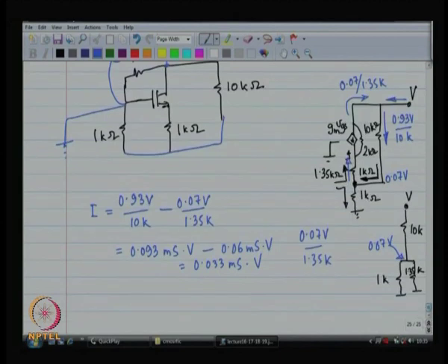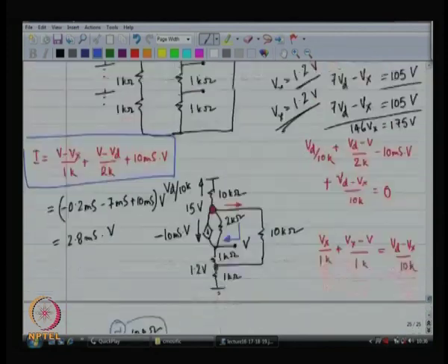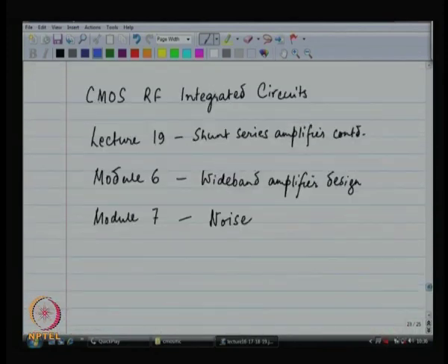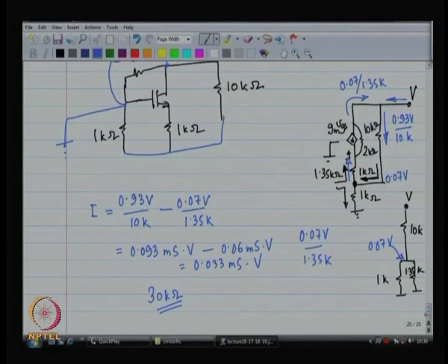That is what you anticipate. 30 kilo ohms or so, right. Now, 30 kilo ohms in shunt with, you have already got a 10 kilo ohms over there. 30 kilo ohms in shunt with 10 kilo ohms is about how much? 23 kilo ohms or so.